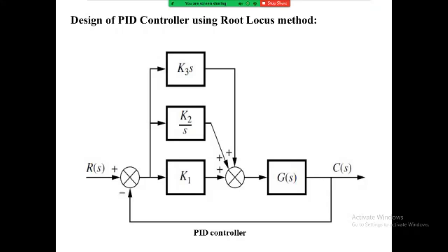The PI controller is the sum of an integrator and a pure gain. It is also called an ideal integrator or integral compensator, and its purpose is to reduce the steady state error to zero. Hence, the purpose of the PID controller is to improve both the transient response and steady state response, that is, zero steady state error.